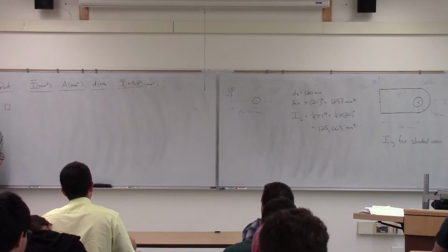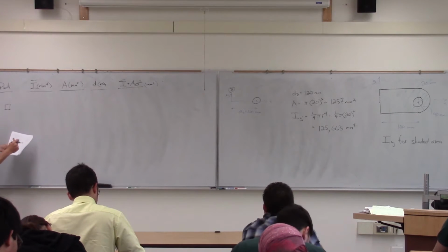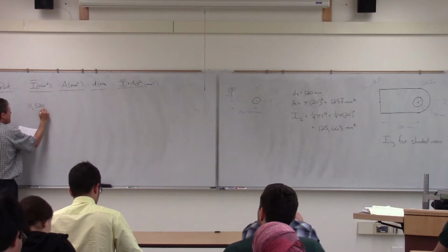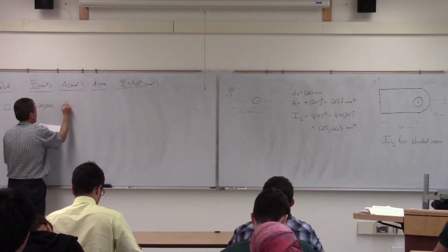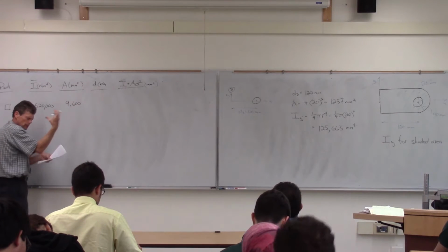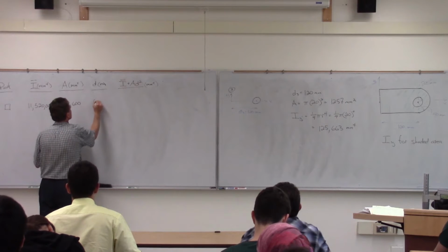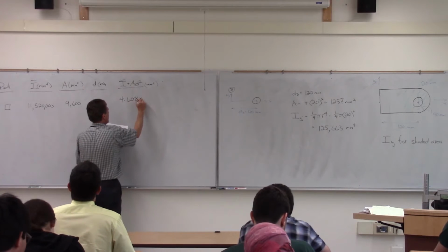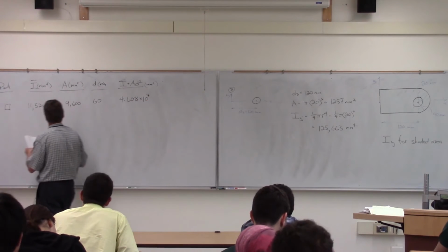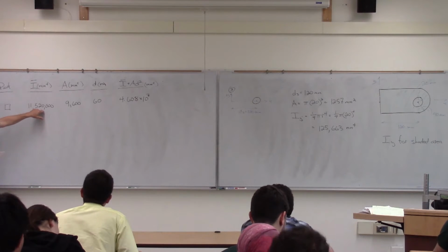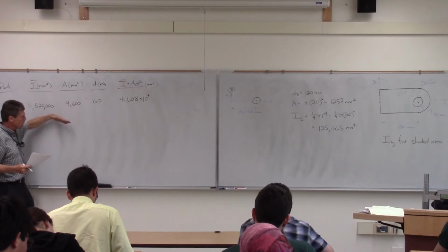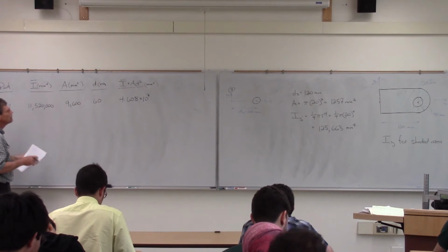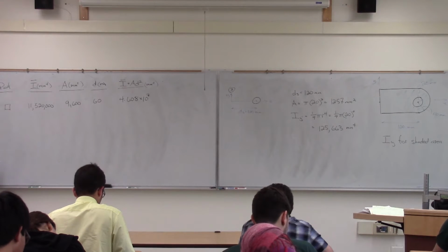OK, so basically all we're going to do is just set up a table like we did with the centroid approach. We're going to have some bigger numbers here. When we get to moments of inertia, we're talking big stuff now. So what we'll do is just simply take those, the ones that we just got done calculating, and establish those on the table. Nice Excel problem here. And then do the calculation for I bar plus A d squared.